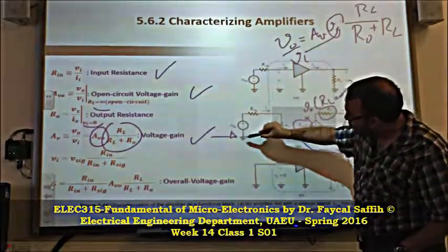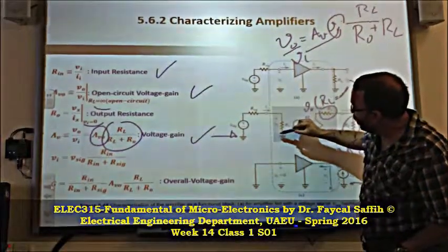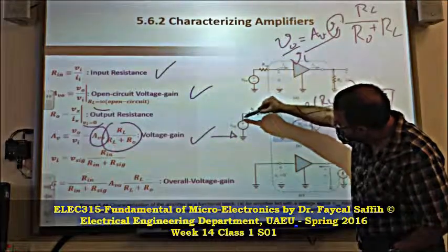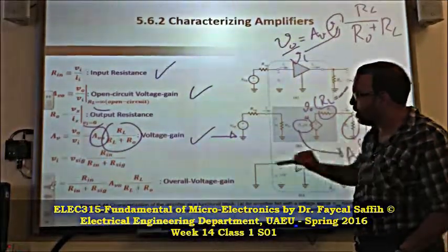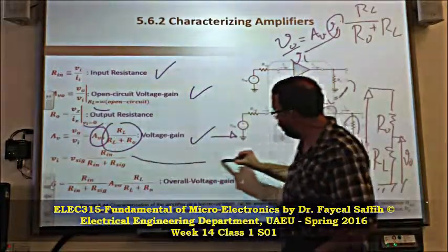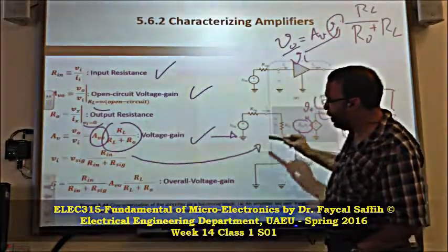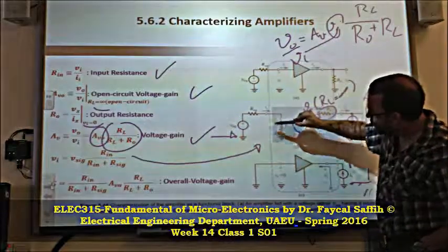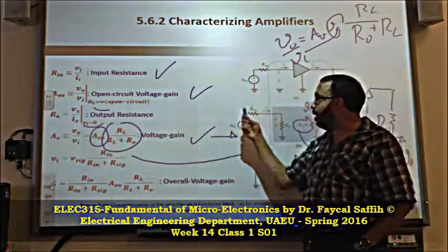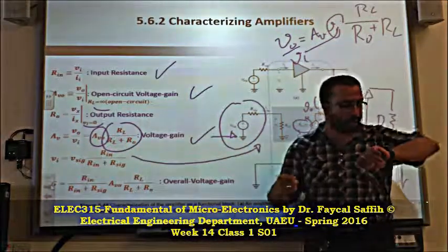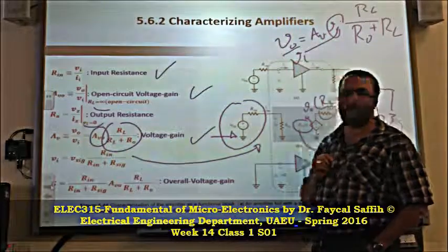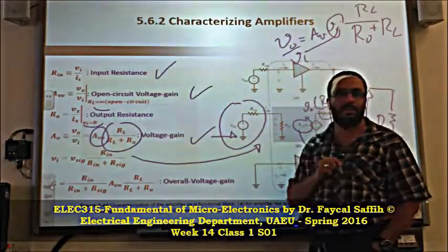This voltage expressed with this voltage is also going to be a voltage divider. This voltage is going to be the whole voltage from here to there times this divided by this plus this, times R in. Here, the input voltage with respect to the input signal, because this is the voltage generator. Any voltage generator has a resistance, and we call it R signal.